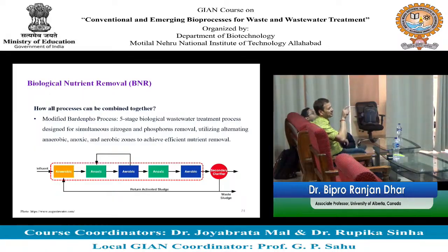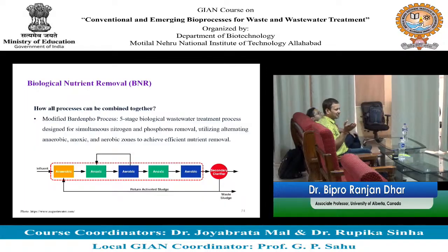Actually, we converted one ASP process like this, in Hyderabad. There was already an existing plant of 30 MLD with an ASP process. Space constraint was also there, so we just added the anaerobic and anoxic processes. Like in most treatment plants, in the aerobic chamber we created zones, such as an anoxic zone.